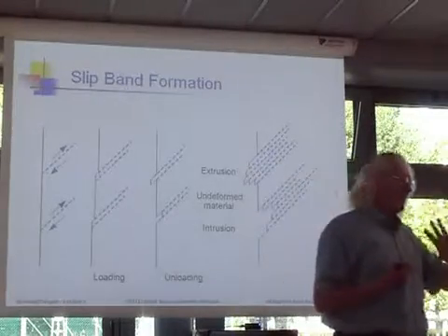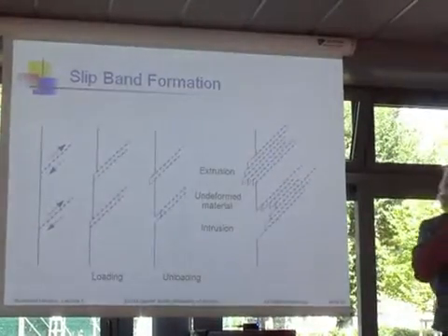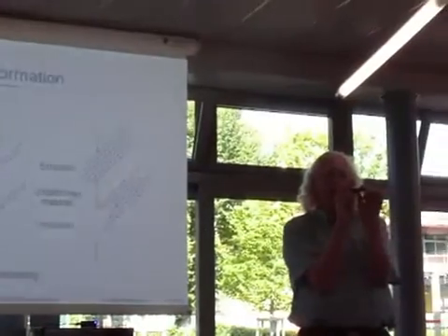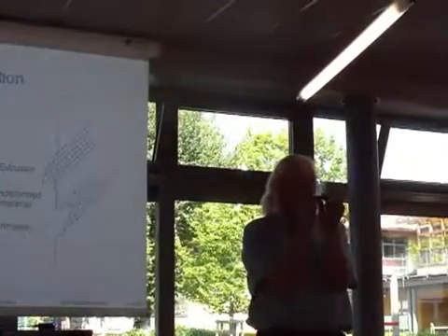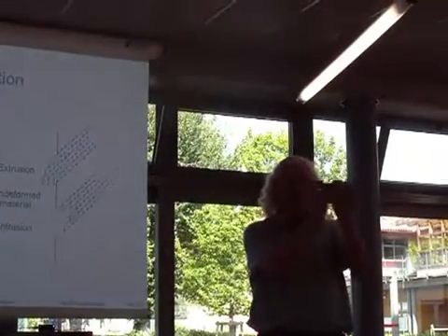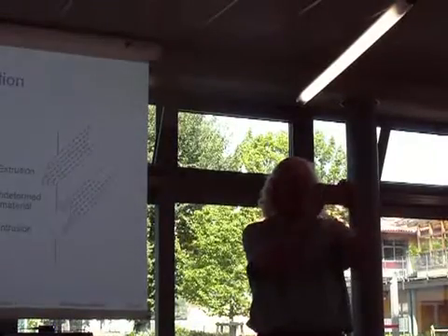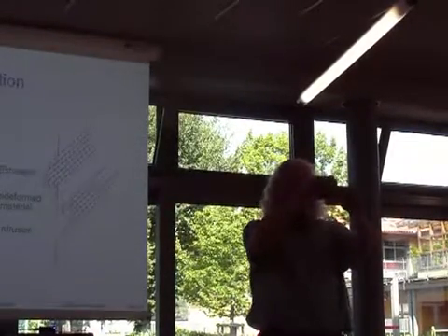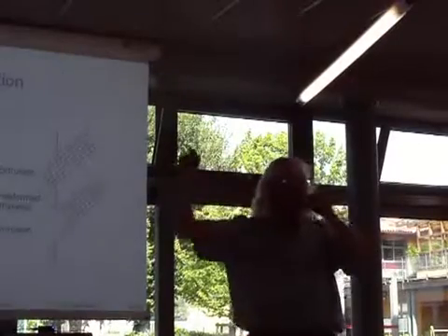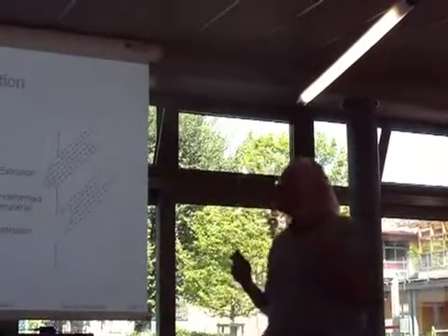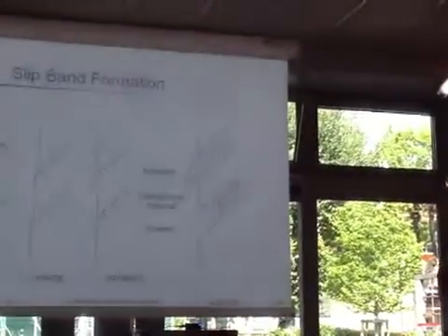And you have all done this experiment, by the way. So you can think about taking a wire. If you bend a wire, you can't straighten it. Now, when you try to straighten a wire that you have bent, then it will bend alongside of where you first did it, and you'll end up with a wavy wire because you moved all those dislocations out of your wire when you did it.